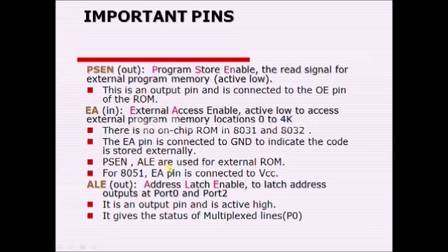PSEN bar, ALE are used for external ROM. For 8051, EA pin is connected to VCC. Now there is one more pin, that is ALE, address latch enable, and this particular pin is going to differentiate port 0, which will be called as multiplex lines. So it is going to differentiate the address and the data information which is carried by port 0. We'll see this later on when we discuss port 0.